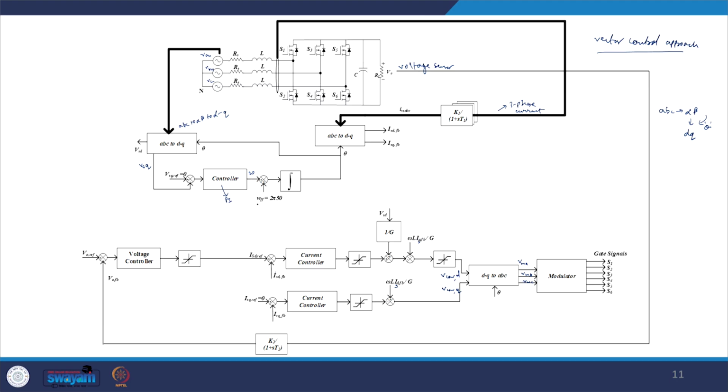From there we are also taking our feed forward term, because mostly our grid frequency, or you can say line frequency, is nearly 50 hertz. There will be slight variation in that frequency, so it varies around that 50 hertz. That's why we have provided that feed forward term. Now this controller has to work to ensure that whatever delta disturbance happens in the frequency is taken care of.